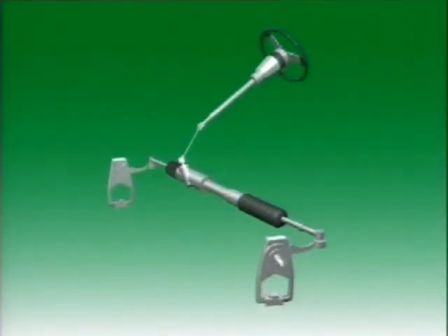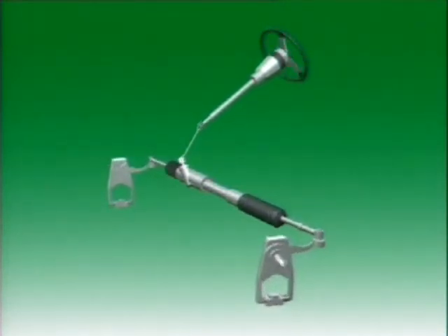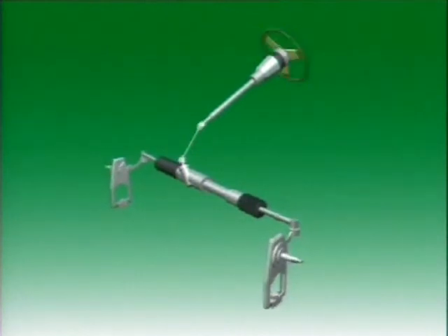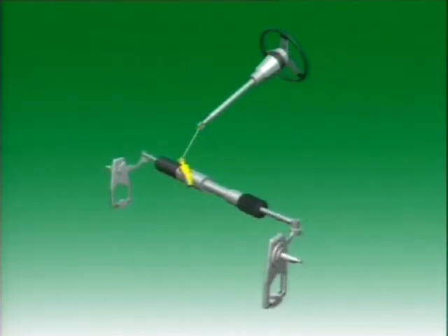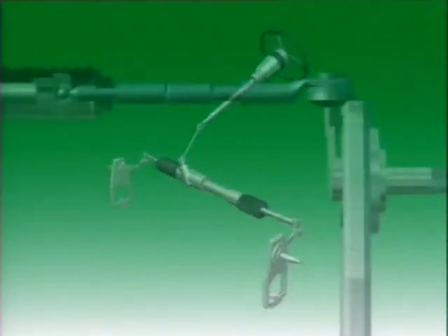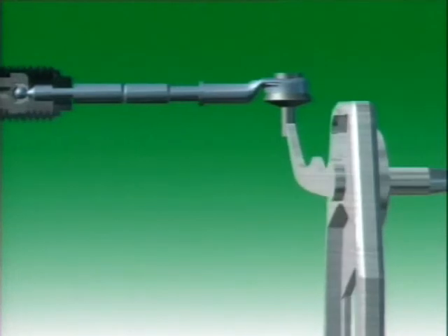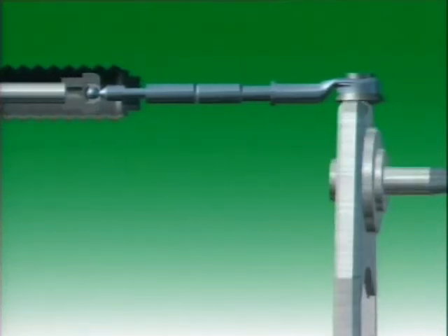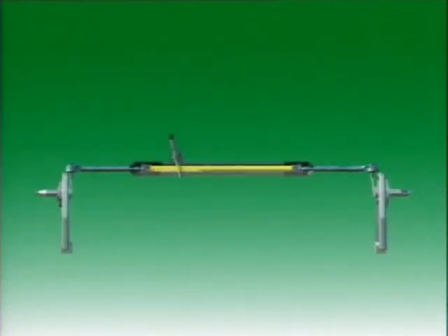With rack and pinion steering, the linkage is simpler since the rack itself is part of the linkage. Movement of the steering wheel is transferred through the steering column, intermediate shaft and universal joints to rotate the pinion, which moves the rack from side to side. A tie rod with a ball swivel at each end of the rack relays the movement directly to the steering lever on each wheel assembly. The rack can thus be considered as the center track rod of a three-piece track rod system.